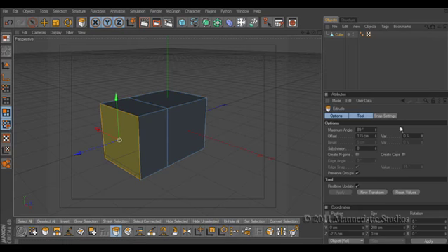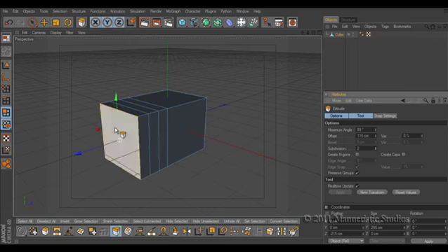You notice in our attributes manager we can control a lot of things too, such as the number of subdivisions. Right now we have 0. Okay, so we can also increase that to 1. You notice that now when we grab the polygon face and extrude it out, we only had one other polygon on each side, which would be 4. But now we add in more subdivisions to make more details. We have a great number of faces that we're adding just by extruding that one polygon face. So I'm going to switch that back to 1 right now.